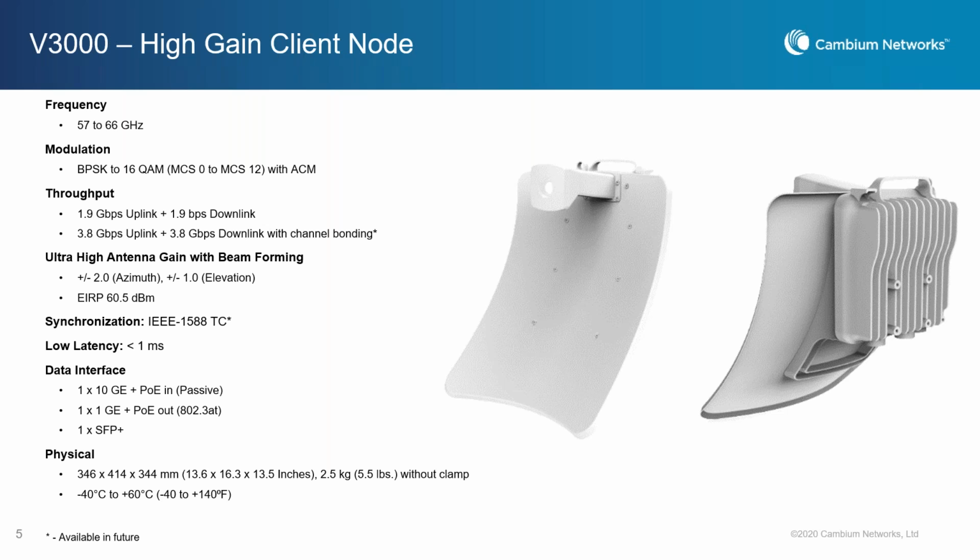And we can also use this V3000 model for a dedicated point-to-point link. When we do point-to-point, we can shoot for over 1,000 meters or 1.5 kilometers. In the extreme case, it's all about link availability and rain rate. So in theory, you can shoot for 4 miles, but then your link availability could be an issue.